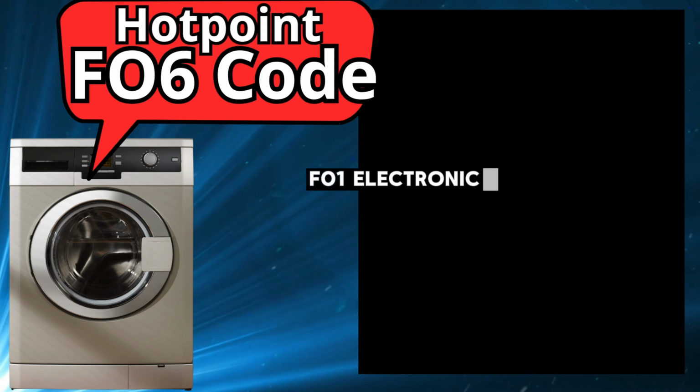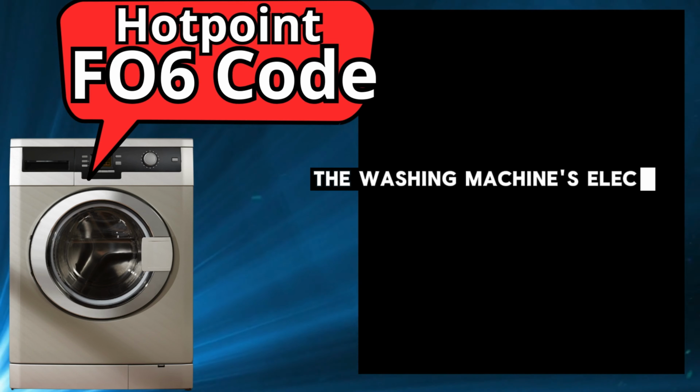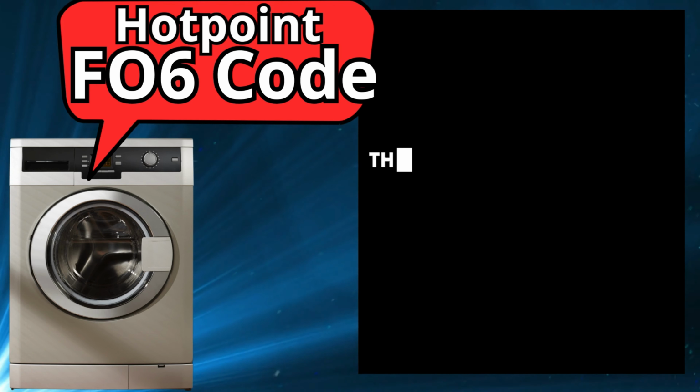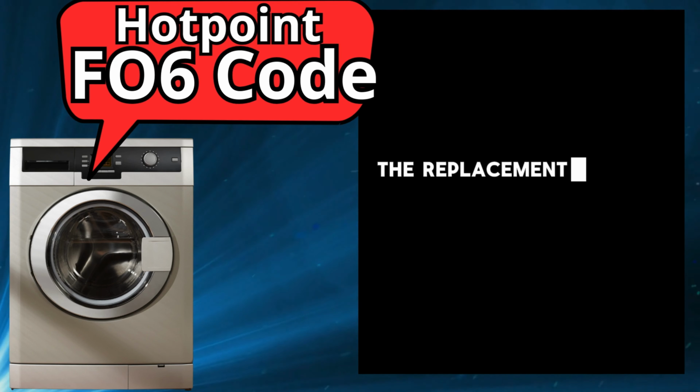F01, electronic circuit board fault. This error indicates a failure in the washing machine's electronic circuit board. As a result, the appliance may not operate at all, or certain functions may become unavailable. This issue often requires a reset or, in severe cases, the replacement of the circuit board.